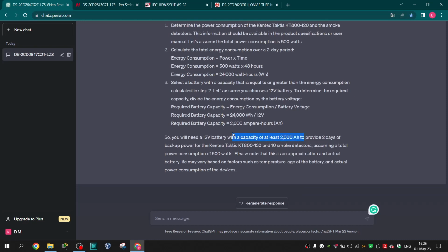And you can see. Of course, you can recalculate it, but just to know, you can ensure your system has a reliable source of power backup by this calculation. But you need to know that it depends on regulations, which differ in each country. For example, the most common is that you have standby power battery and alarm state, and then you add some 25%, for example, as safe margin on top of the total, and then you have how many batteries you need. ChatGPT doesn't know anything about that. Basically, it can just help you understand or calculate this brief kind of calculation for the battery.